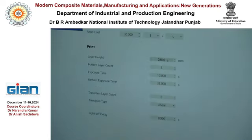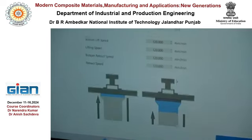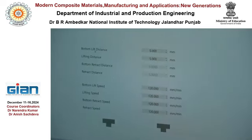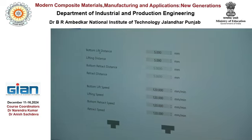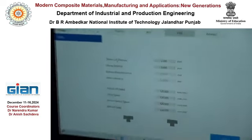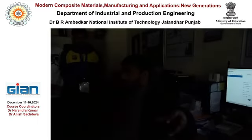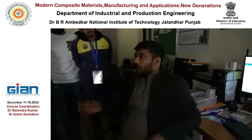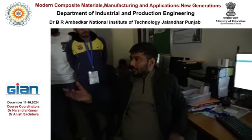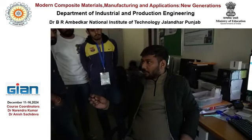This one is the bottom lift distance. After printing a single layer, the platform will lift upward so that the liquid material can fill in between the platform and the base, because the liquid has a viscosity of around 150 cP, centipoise.